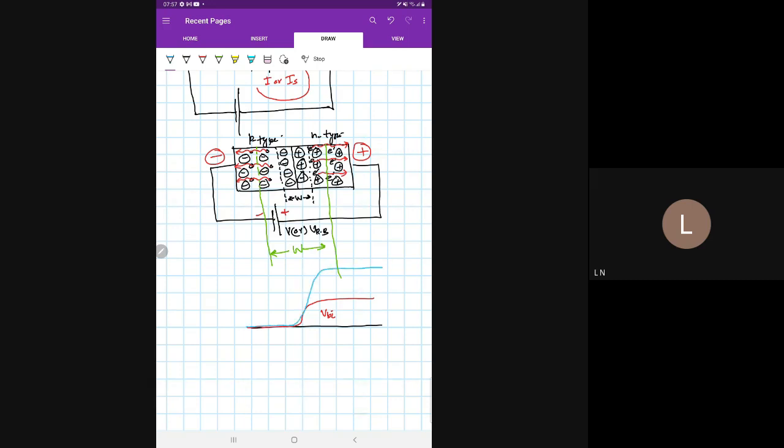The depletion region is more wide and more potential is required for these charge carriers to cross the barrier, because the barrier is now wider and larger. So additional energy will be required. Due to VRB, the potential also increased, and the effective potential to cross the junction will be higher now.